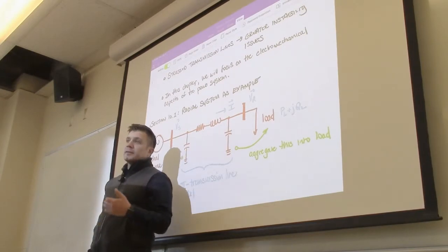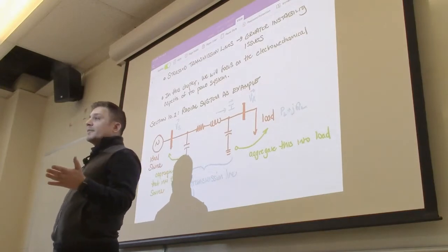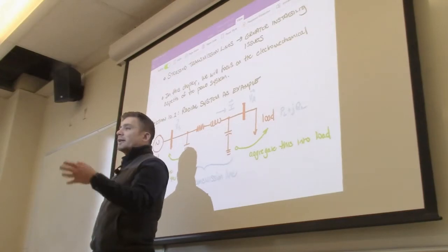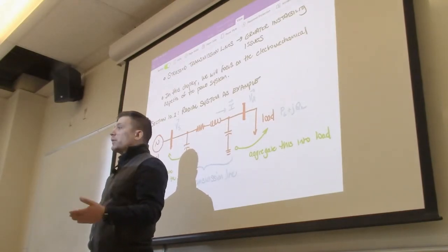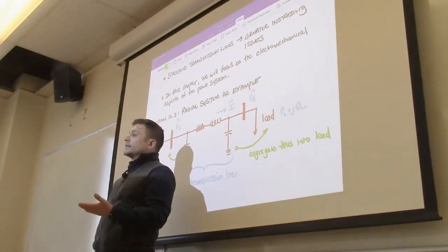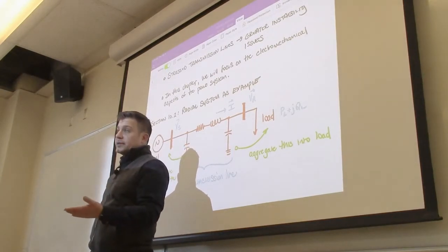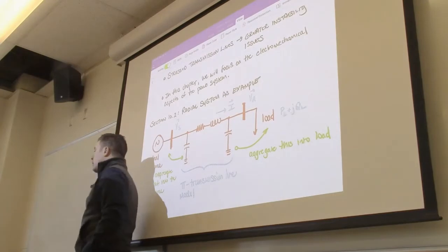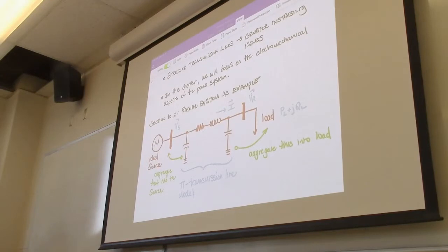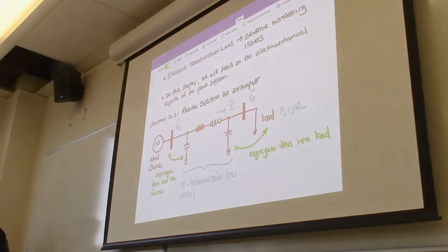And that's where we're going to look at systems with 5, 10, for the project, potentially even larger numbers of buses. But in Chapter 10, at least, we'll have more than just a generator connected to an infinite bus. We'll be considering transmission effects. We'll be able to use reactive power control via excitation in combination with power factor correction using capacitances or shunt values. So we will be building upon what we had done over the last couple weeks or so.